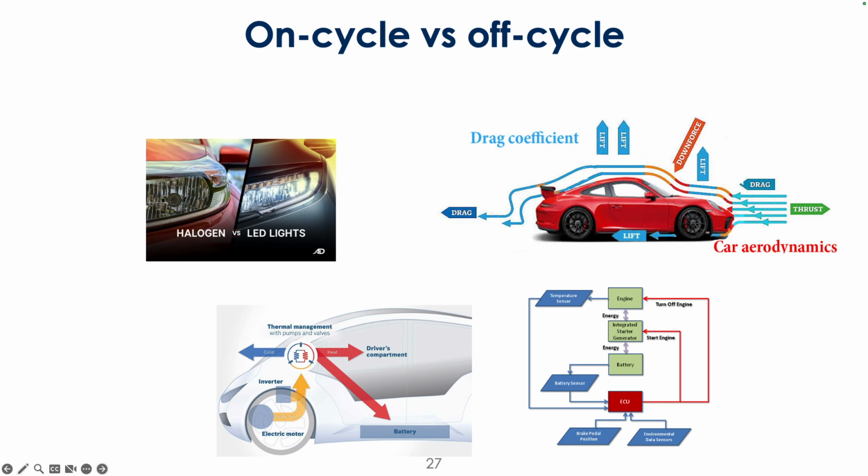The AC and thermal management part isn't going to show up outside of the air conditioning load in one particular test. The aerodynamics of the vehicle can affect efficiency a lot. That's not even going to show up on any drive cycle test, because that only shows up when you're moving the car through the air.